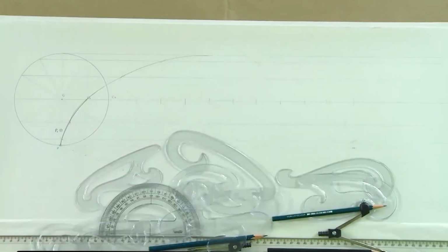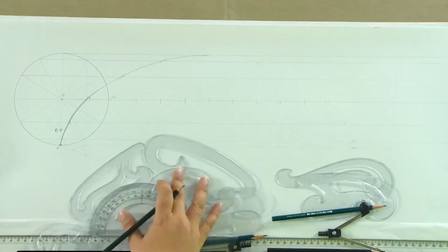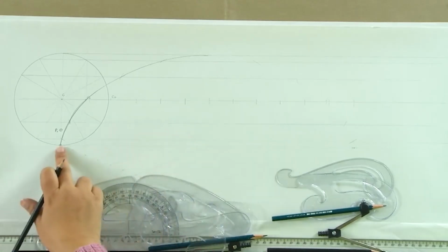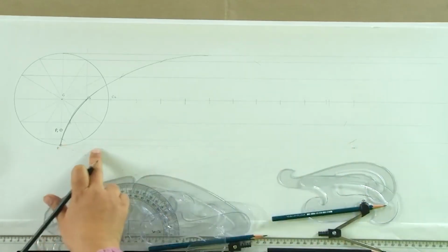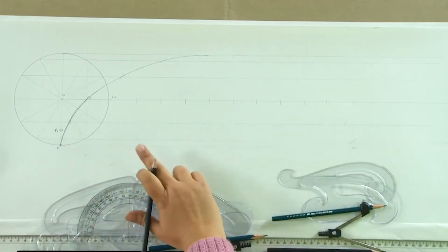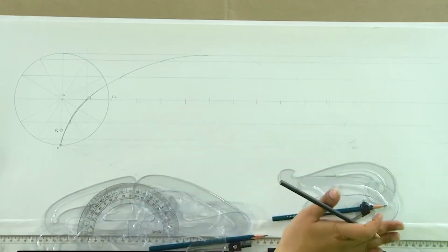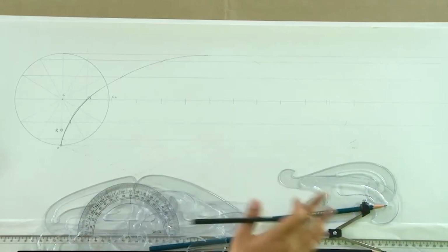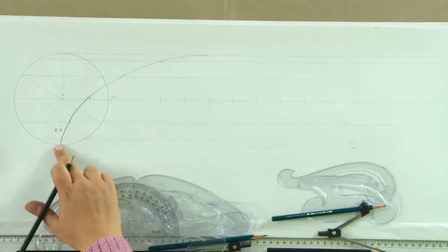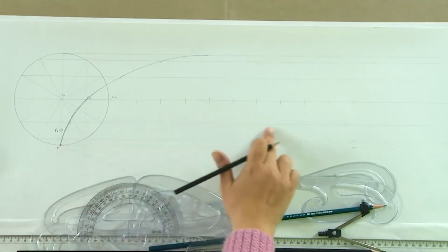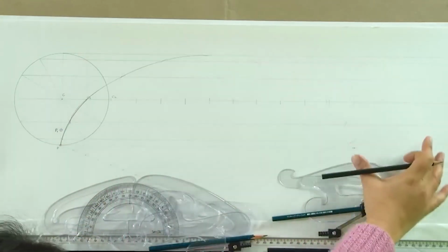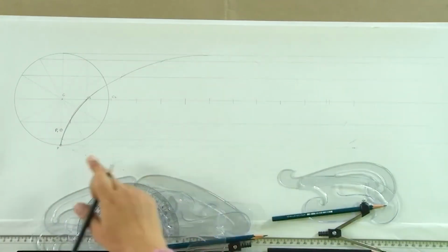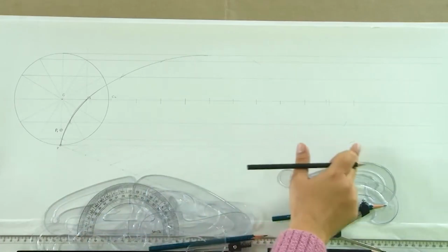If we are to draw epicycloid, in that case the only change is that this length of the circumference which we have drawn as a straight line would actually be taken on a circle. So, whatever circular path the circle is going to trace, we would take the arc of that circle where this smaller circle would be moving, and that circumference would be divided into equal number of parts.